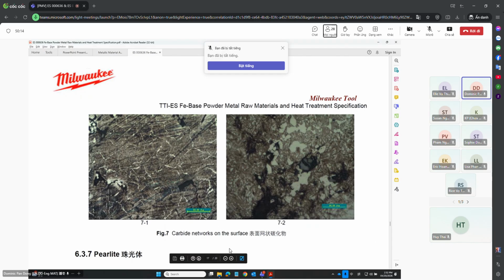On the left, you can see something like a spider net, those shiny white, thick layers. It is the so-called carbide network. This network is fragile and very easy to crack. Even though the hardness is good, the brittleness is so strong that we don't want to see it. It's not accepted. On the right side, we see large white particles, like small rocks broken into pieces. Those are also brittle and pretty hard parts inside. It would destroy our parts' ductility, so it's not desired.